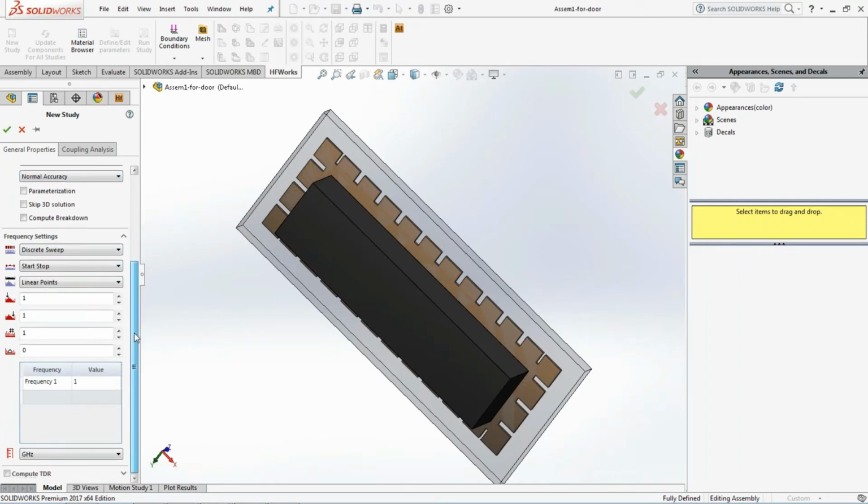We define our frequency range. For example, for this one, our frequency is 2.45 gigahertz, that's the ISM band. But let's say we're going to monitor the leakage from 1 gigahertz to 5 gigahertz, and we can decide how many frequencies in between. Let's say I'm going to check 41 frequency points in between, which means frequency steps of 0.1 gigahertz. So I will simply define my study.